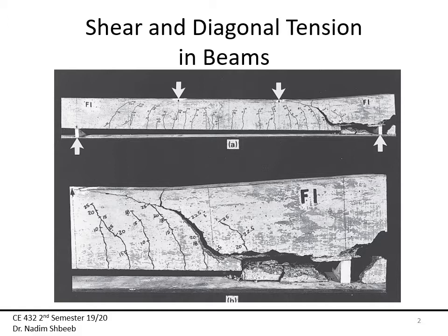But since this can't be done at the present time, what we have in front of you is a 4-point bending test. There is no web or shear reinforcement in here, and we can see the different zones. There's almost like 3 zones. Let's call this zone 1, zone 2, and this is similar to zone 1. So in this area here, we only have pure flexural cracks, as you can see.